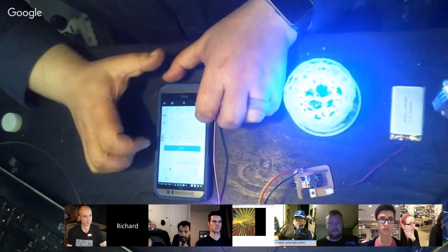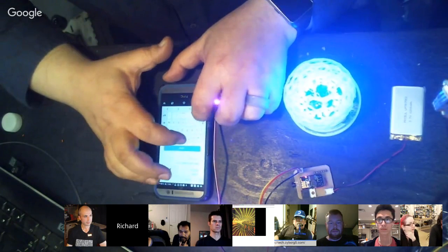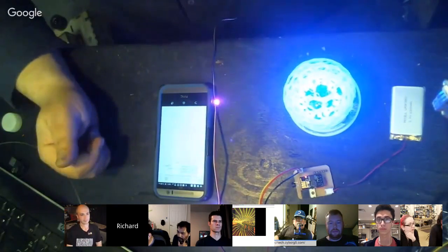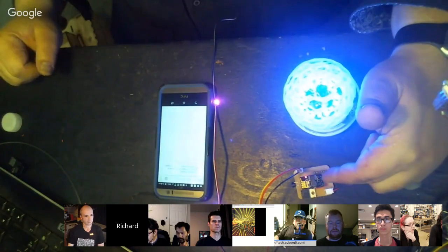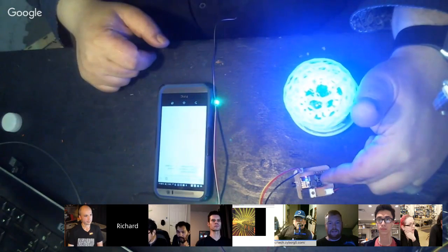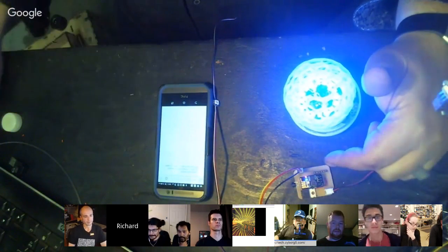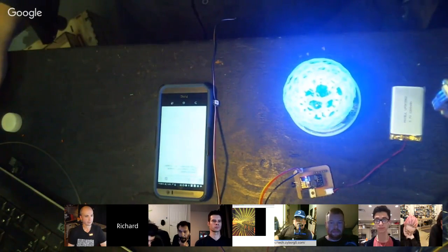And then it will retain that until it experiences another network that it's unfamiliar with. Then you have to go through this process over and over again. So it's going to connect here in just a minute, and you should see these lights turn green briefly and then off. So the green and off, and now that's connected. And I can then change the colors on Adafruit IO.